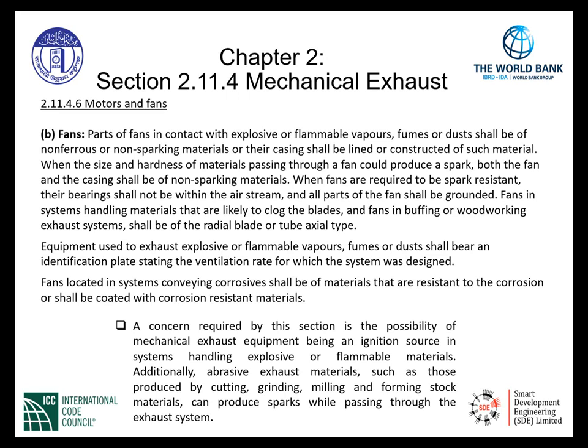Continuing on with the requirement, it indicates where fans are required to be spark resistant, their bearings shall not be within the airstream, and all parts of the fan shall be grounded. We don't want any type of high temperatures resulting in a bearing failure that would create a hot surface and possibly ignite flammable or explosive vapors or dust or even fumes within the airstream. That's why we have this particular requirement.